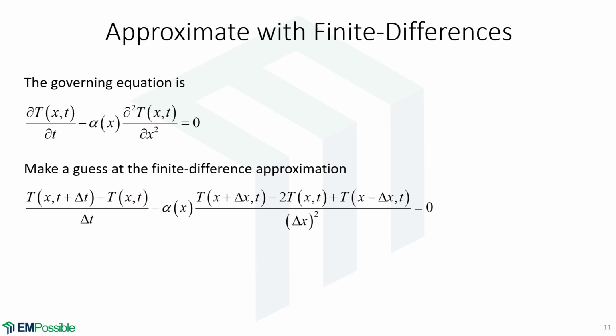That's a first order derivative. No derivative happening to our thermal diffusivity, so that just comes down here. But we have a second order derivative of the temperature with respect to x. So here's how we approximate a second order derivative. It's the temperature at the next point minus 2 times the temperature at the point x plus the temperature at the previous point, all divided by the grid spacing squared.